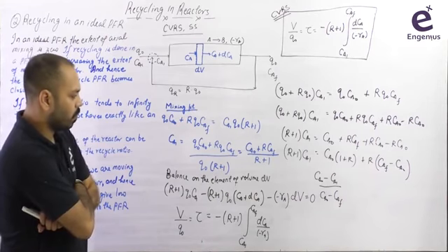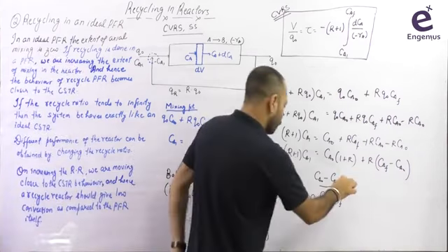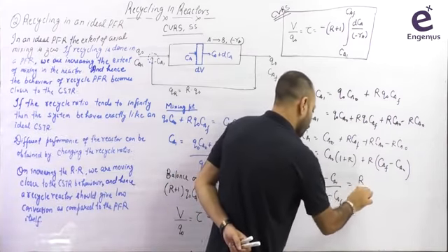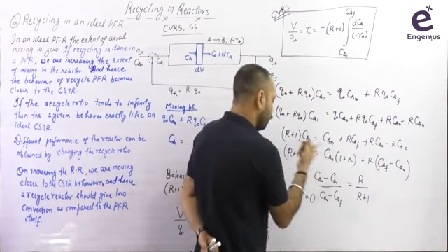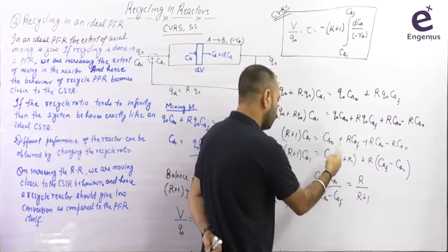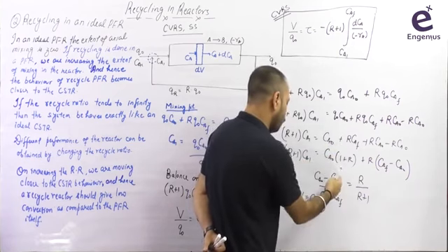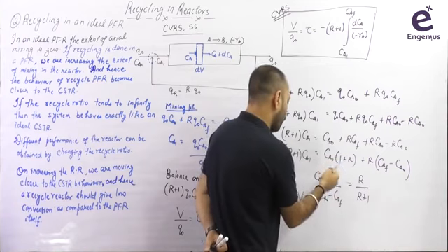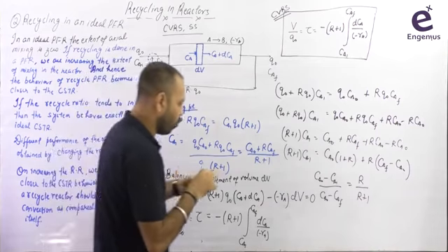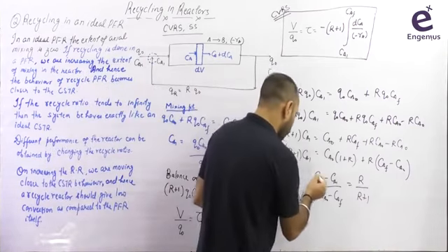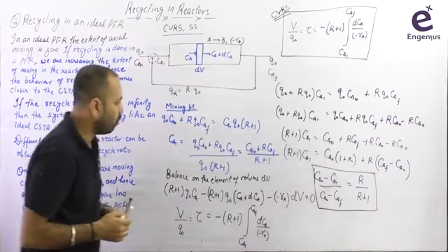Can you tell me the relation becomes equal to, I guess it will be equal to R by R plus 1, right? Let me check this again. CA naught minus CA1, so that is 1 plus R into CA naught minus CA1, and that must be equal to R into CA naught minus CAF. Yeah, fine. So CA naught minus CA1 by CA naught minus CAF is equal to R by R plus 1. This is one relation. Why am I writing this relation? So that I'll be able to explain the graph easily.